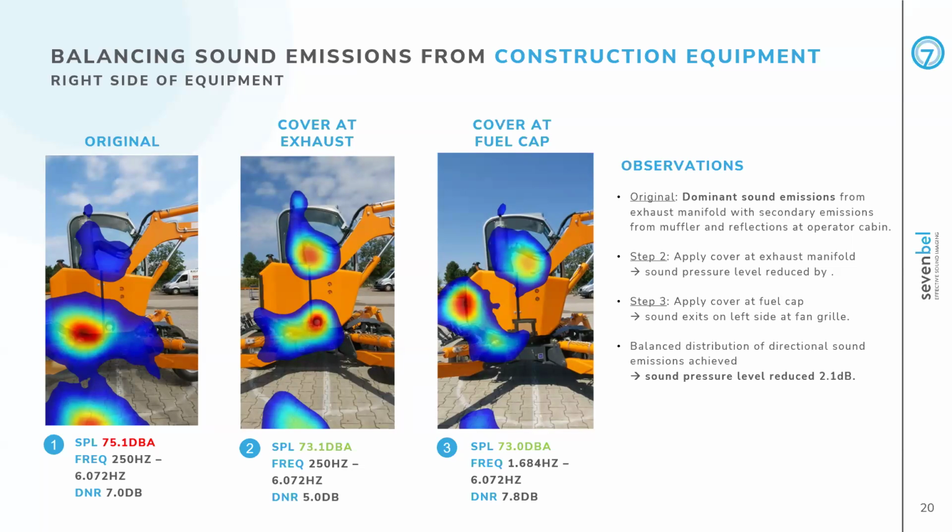And the nice thing with acoustic cameras is that you can easily identify, not only by our software, which essentially does that identification automatically, but you can also prove yourself whether all of the microphones are working by checking the so-called available dynamic range, which is at least 13 dB for our acoustic camera technology. So, to make a long story short, a calibration speaker is included. It's used for aligning the optical image with the acoustic image, and at the same time it helps you check that all of the microphones are working at the correct sensitivity level. Overall, the equipment is maintenance free.